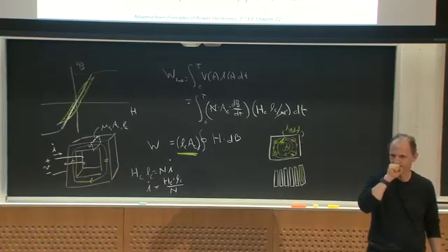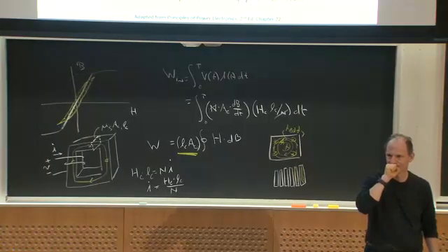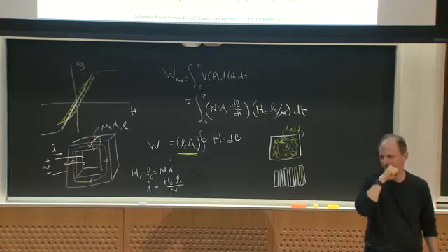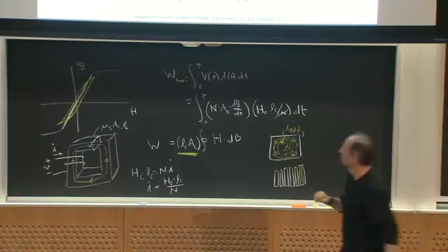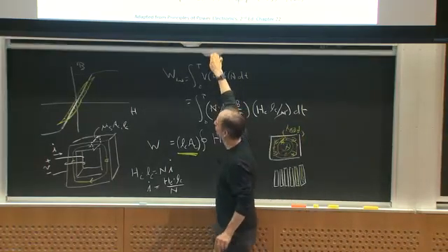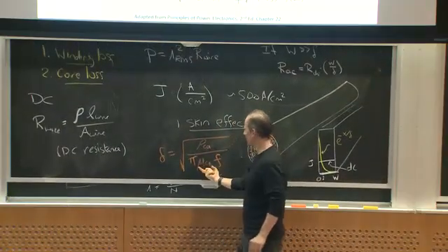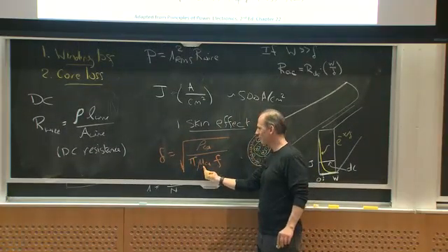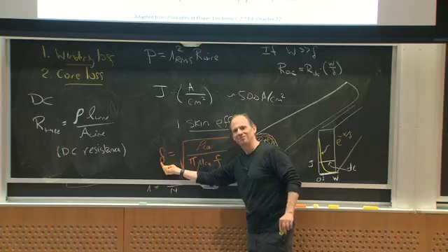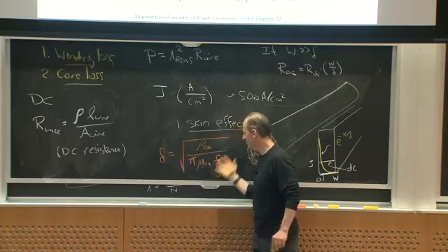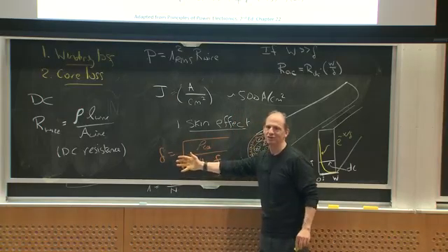Characterizes a magnetic core as being higher or slower frequency? Is it related to permeability, or is it some other property? Well, it comes down to what the skin depth is. If you have high permeability, the skin depth gets small, right? So you just plug this in and find out what dimension you would care about.